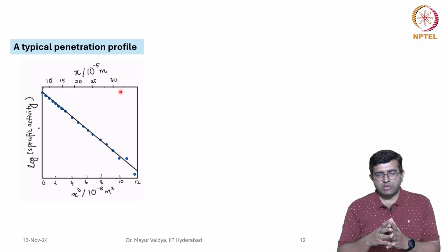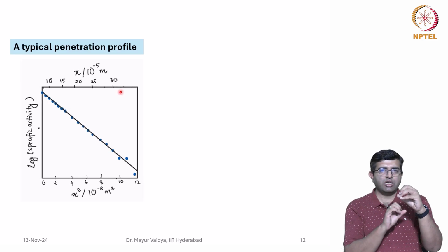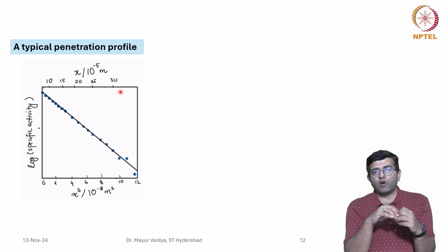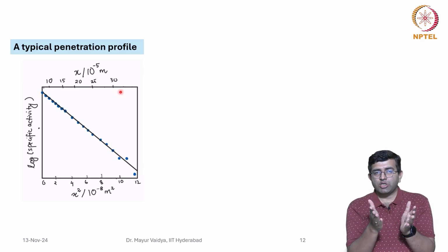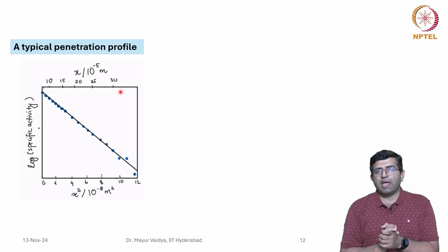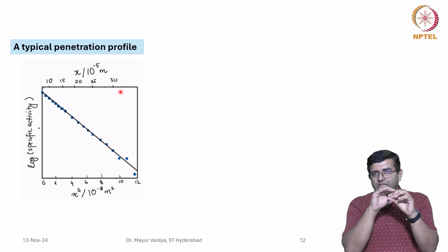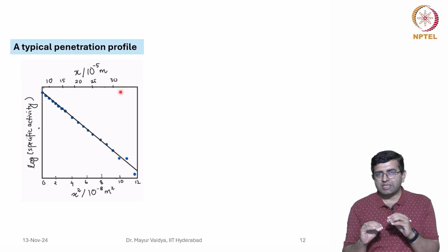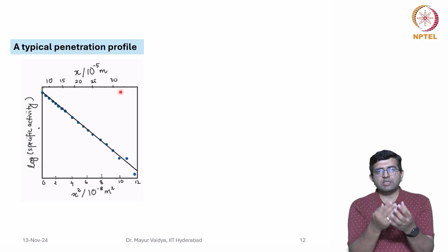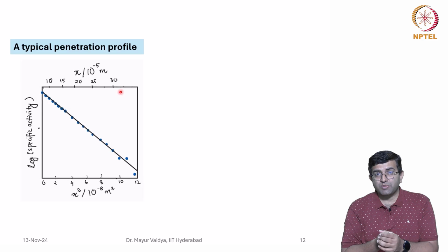But when you are measuring diffusion coefficients at lower temperatures, the diffusion depths may not be high enough; they may be very small, even in the range of nanometers. In such a case, you cannot section nanometers using mechanical sectioning, because even at the smallest speeds it will take out sections in the submicron regime at least.